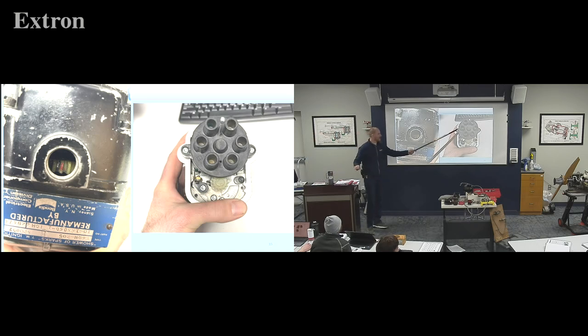This is Slick, yeah, correct. The plastic part is the same, it's the same part number, if you will. So instead of making 2 separate ones, they're like, well, you, Mr. Mechanic, you just have to know, if you're pinning a right-hand mag, put it in the right hole. If you're pinning a left-hand mag, put it in the left hole.